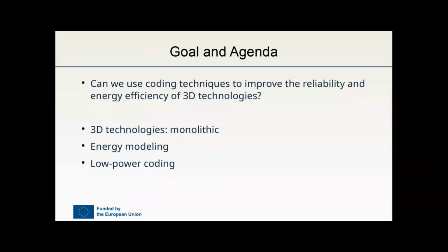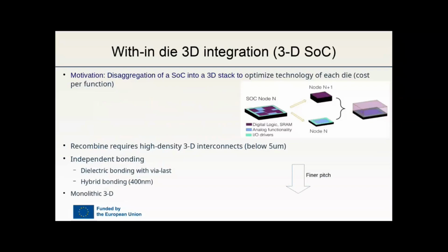What we are going to develop is a very small module fundamentally based in a set of XOR gates, which is able to reduce most of the, let's say, redundancy that we have in the data, just with a cost which is fundamentally proportional to the number of lines, so extremely small.